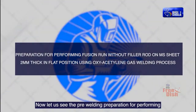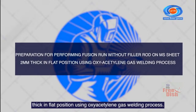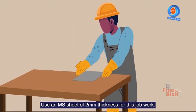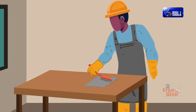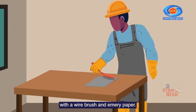Now let us see the pre-welding preparation for performing fusion run without filler rod on MS sheet 2 mm thick in flat position using oxyacetylene gas welding process. Use an MS sheet of 2 mm thickness for this job work. If there is any rust, remove it with a wire brush and emery paper.